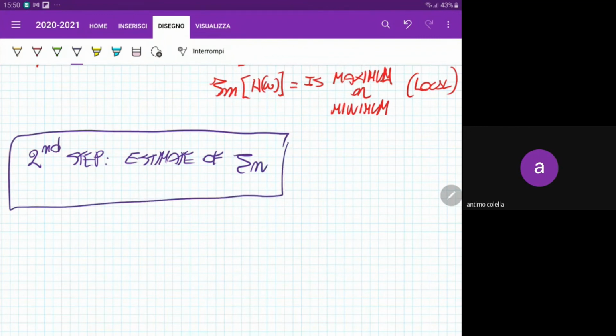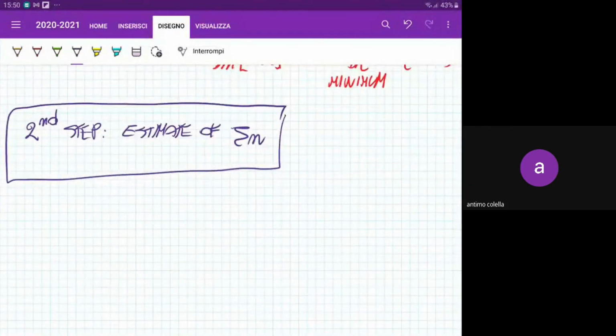In order to estimate the damping ratio, we have to refer to some analytical details. Okay. In order to do that, let me consider to evaluate the average power that is dissipated in a period from the viscous force, okay, that is characterizing your damping, okay, when we are exciting the structure with harmonic excitation, okay.